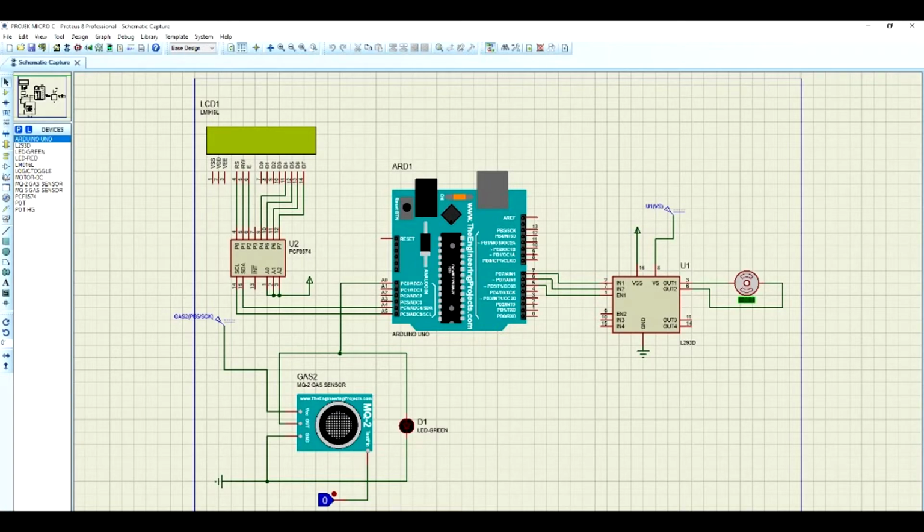For our connection circuit, as you can see here, we connect 7 pins to the input-output expander for I2C bus from the LCD I2C, and then pins 1, 2, 3 at the input-output expander for I2C bus, we connect to the power, and pins 14 and 15, we connect to pins A5 and A4 at the Arduino Uno respectively.